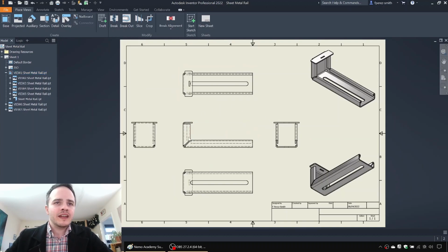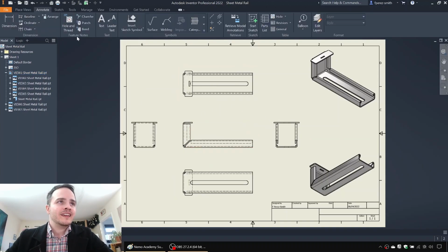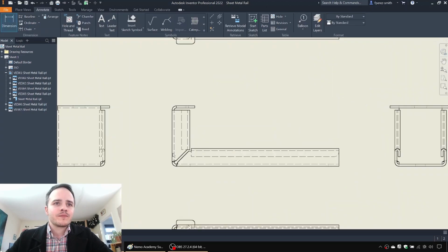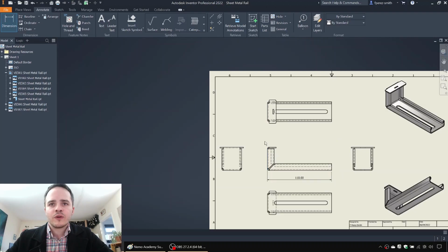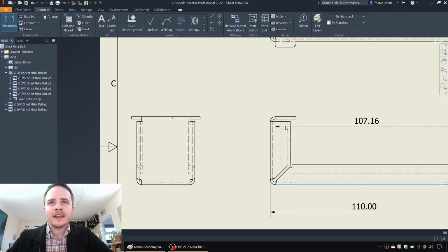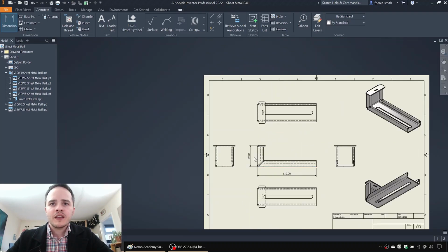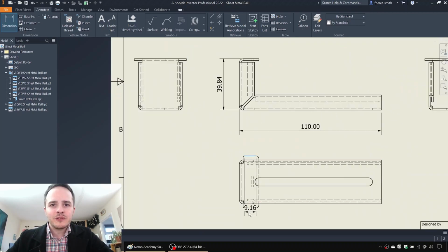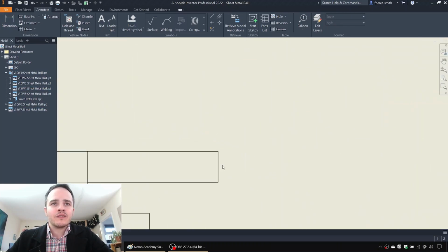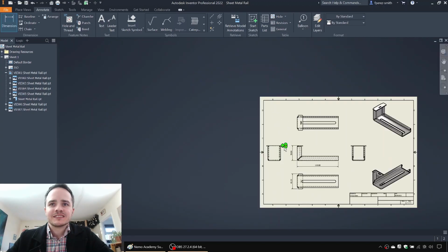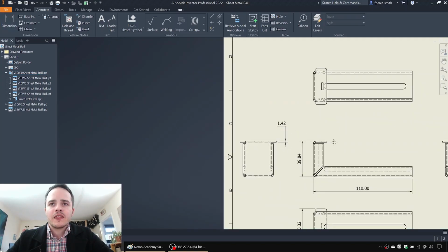Go ahead and put in our drawing dimensions, annotate, and we'll say dimension. And again, there's a million tools that you can use for drawing. For this video, we're not that interested in the details, but I'll quickly put in the major dimensions so we don't feel too bad. At least we can say we tried to do a drawing. Very good. And very importantly for this sort of thing, it'd be very useful to have the dimension of thickness, which represents the thickness of the sheet metal.